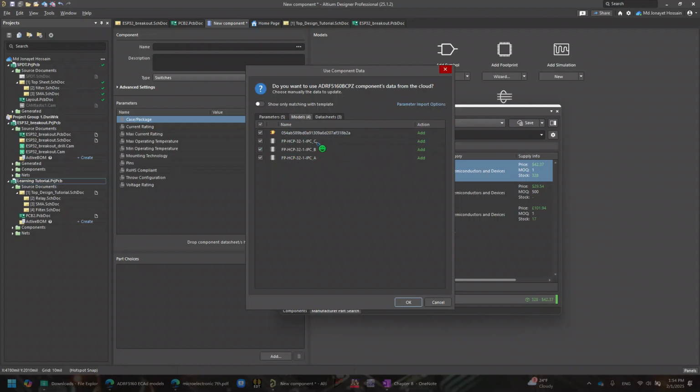A, B, C are important. It basically shows you different versions of it. I might just go with B for now. B is most of the time the nominal one. It basically means that based on your soldering system, it will have different types of footprint. Sometimes your pads are a little wider, so that when you try to do soldering, it helps your solder flow much better.